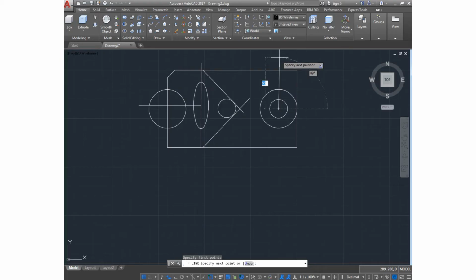The distance I'm going is the radius distance. I'm doing this because you cannot start drawing the line at the top of the circle. So 25, press enter. Then move an unspecified distance, but make sure the angle is 180. Okay, click there, escape. Repeat the same process.